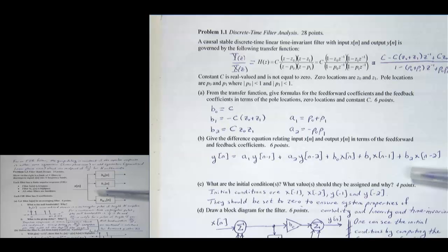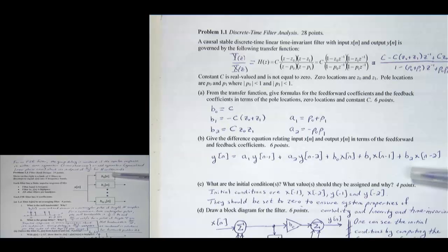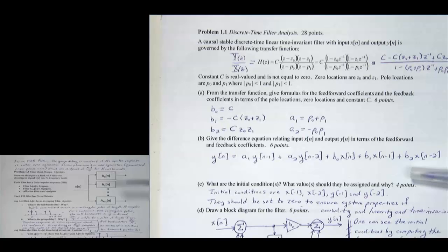The same input goes through all these filters in parallel, and the output here will depend, of course, on your low-pass filter design. The way I've set it up is this low-pass filter should have a bandwidth of 2 pi over n, right? The whole frequency band in discrete time goes from minus pi to pi, which is 2 pi in width. So if we divide that into n subbands, we should get 2 pi over n as the bandwidth.